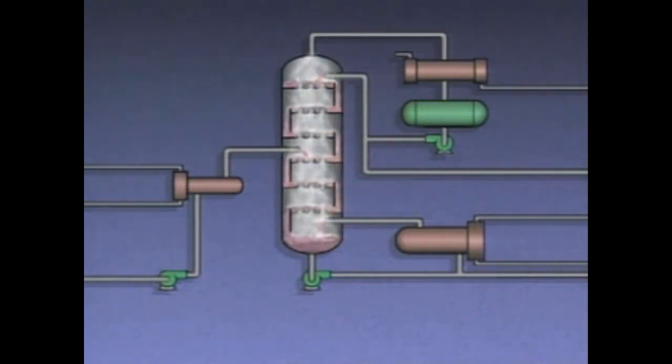The surging of liquid up and down a column can sometimes damage internal structures of the column. Besides the causes we've described, overloading and flooding can also occur when vapor and liquid flows become restricted by scale buildup or damage to bubble caps or packing. But regardless of the cause, operators must be able to identify the problem so that it can be eliminated.